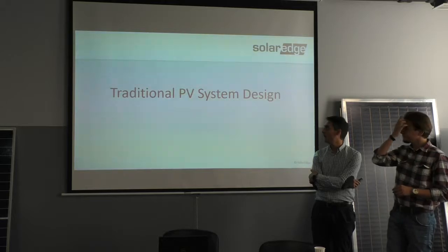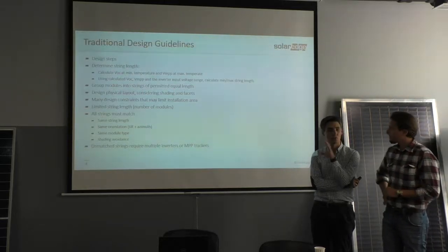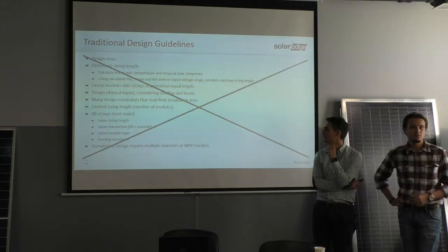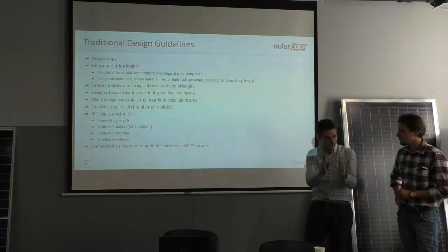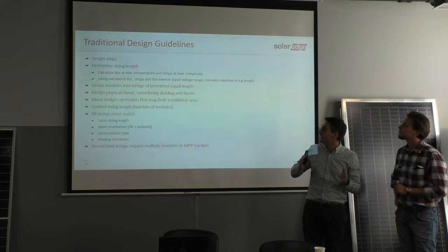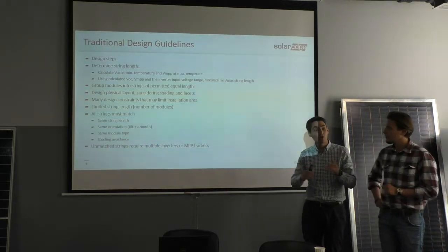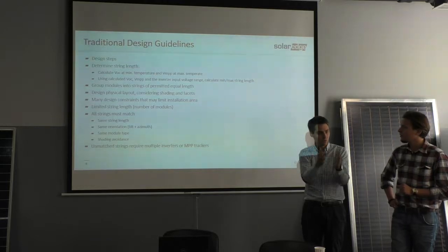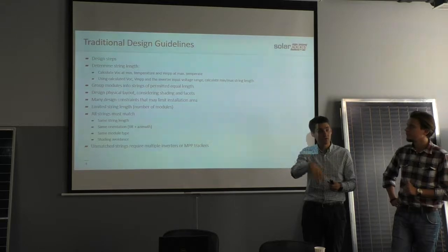If we are talking about traditional PV system design, we have to follow some rules. First of all, in the case of a standard inverter, you have to define VOC at the minimum temperature and VMPP at the maximum temperature, so voltage at the maximum power point at minimum and maximum temperature.